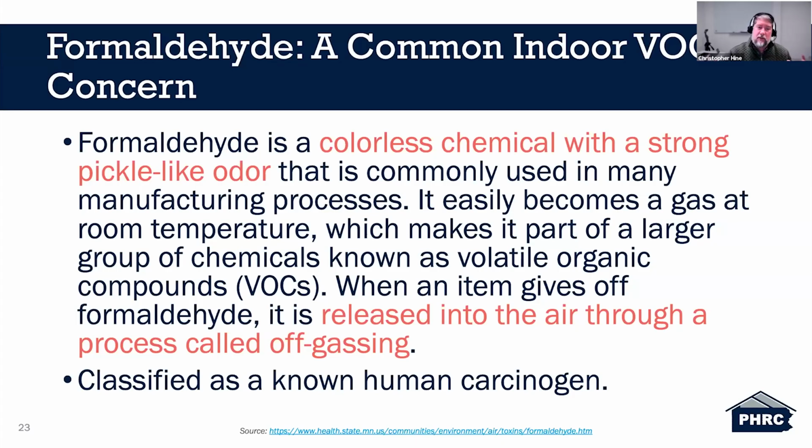So that chemical is within those building products when exposed to room temperature. In most VOCs, and formaldehyde being one of those, when you increase the temperature and you increase the humidity, it actually increases the off-gassing of that. It makes it more potent. So I do touch on, it's also good to keep the temperature and humidity in check. Formaldehyde is classified as a known human carcinogen, right?